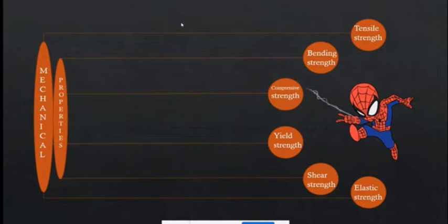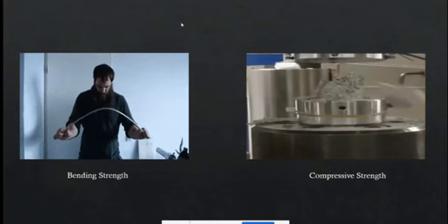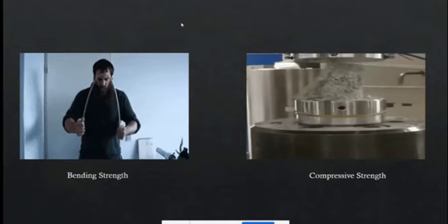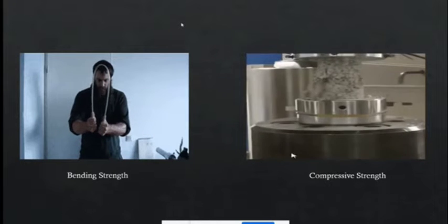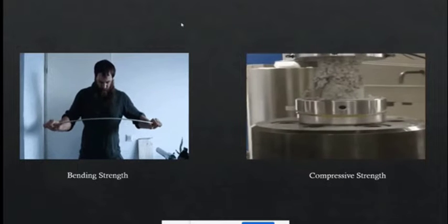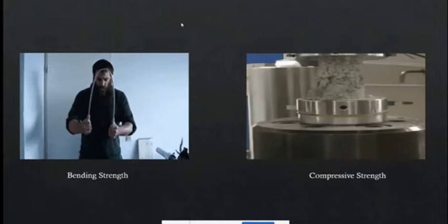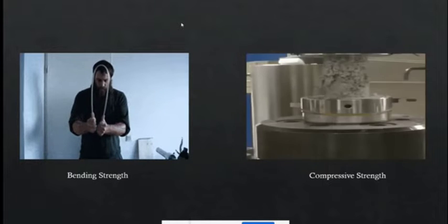and elastic strength. First of all, bending strength. It is the maximum stress that the cross section is subjected to when the load is applied between the 2 points of the specimen. Its unit is Newton per mm square, and it is one of the indexes of material strength.